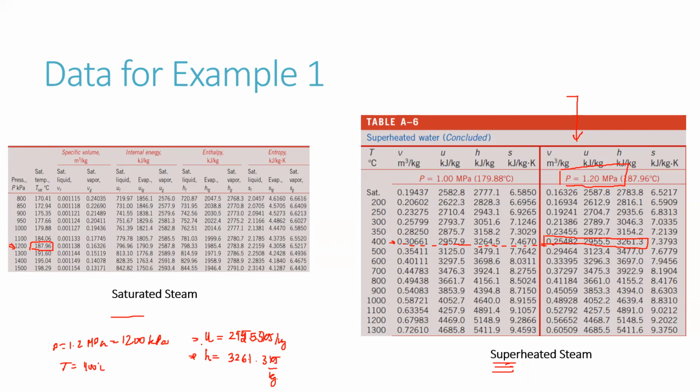Okay, now see what is happening in the question. They are saying that we have taken a pipeline and connected it to a rigid tank, which is initially evacuated. So initially, the mass is 0. And then mass is being admitted here from a constant pressure of 1.2 megapascal.